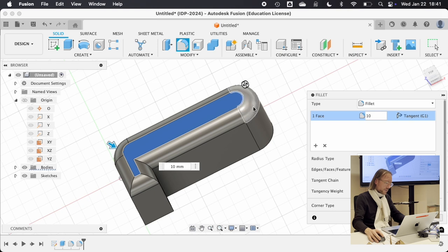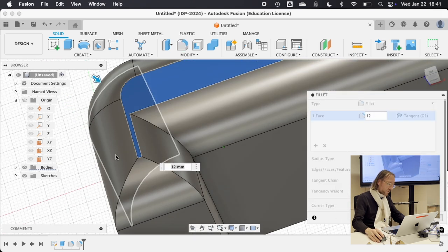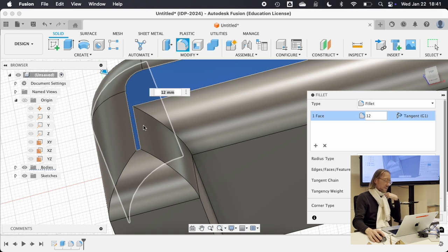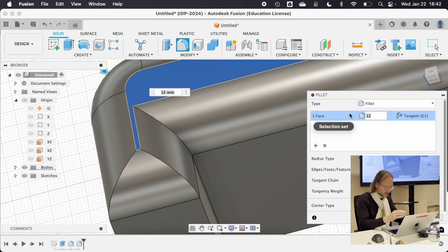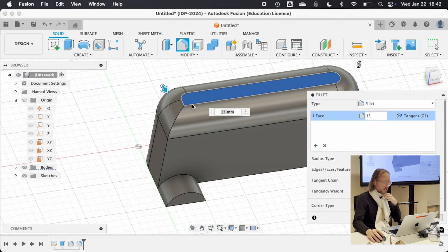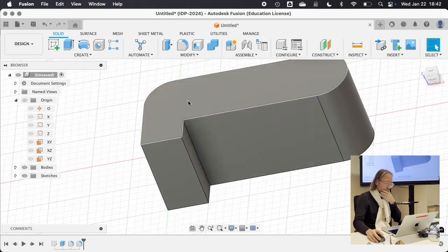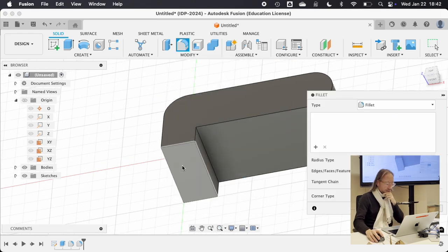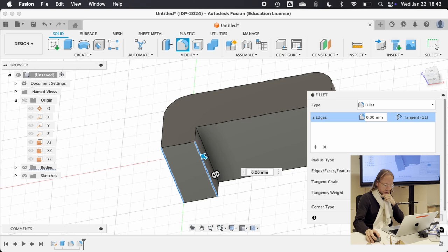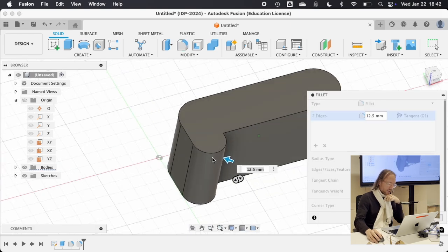it keeps getting bigger, but there's a point where the surface geometry will create a self-intersecting boundary, and that's just over 12.5. So if I do 13, something weird is going to happen. Okay, in this case, it just deleted all its geometry, but I don't want that. So I'll finish the body by adding rounds to these two. And these ones I'll do 12.5 for the handle.